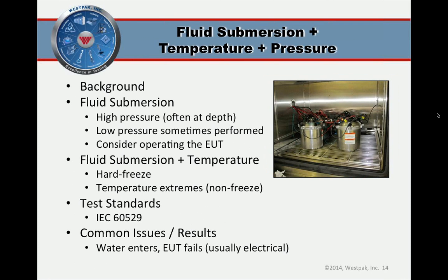So the idea here is if you have your product and it could be submerged in fluid, either more or less at sea level, like in a pond or puddle, or with depth. So imagine if you're 10 meters underwater scuba diving or something similar, we'll simulate that here. So what we have are pressure pots. We'll put the product in the pressure pots, submerge them with fluid, and then put a head pressure over that using air to simulate the depth.